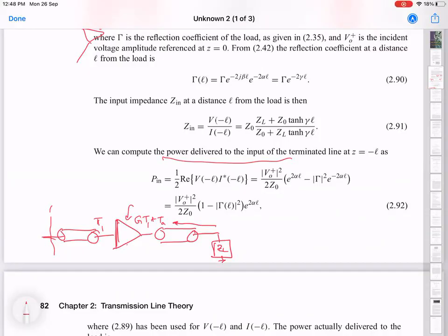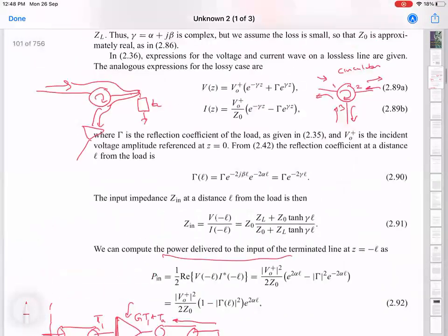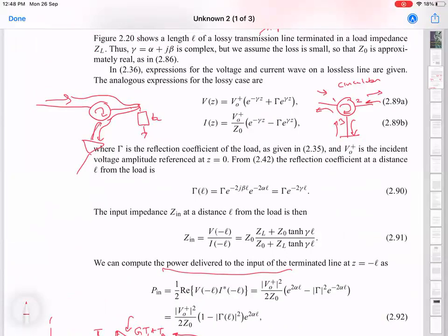So when you use a circulator as well as an amplifier, that amplifier goes in this line and it only amplifies the signal which is going away from the device, which is coming back to your receiver. The signal which reaches the actual device whose reflection coefficient you're measuring is still this signal, which has not been affected by the amplifier. Will it also amplify the Johnson noise? Yes, it does, but it's now going in the output direction, so you don't care about that. The worry is that this Johnson noise doesn't reach your device.